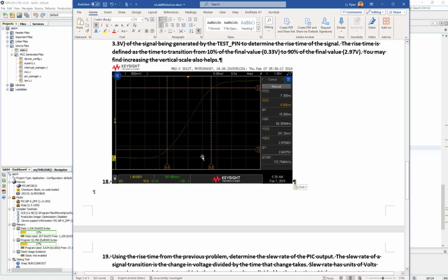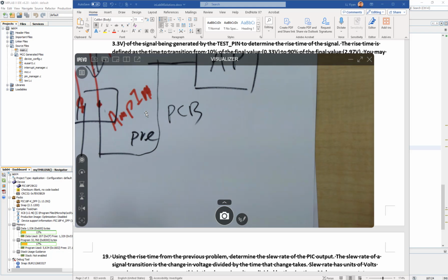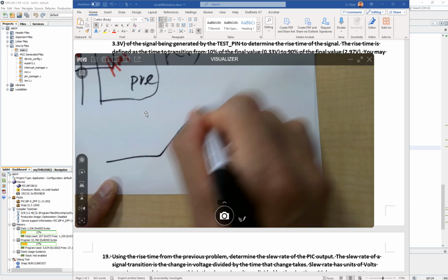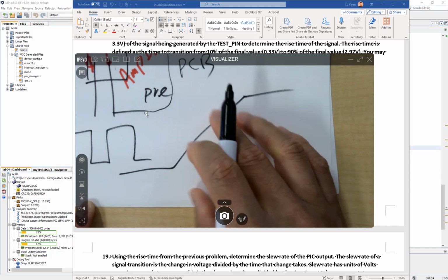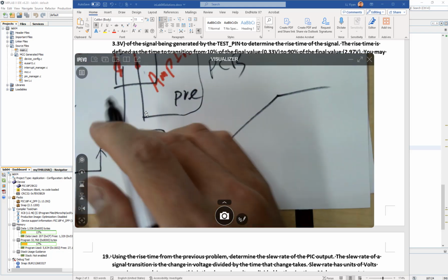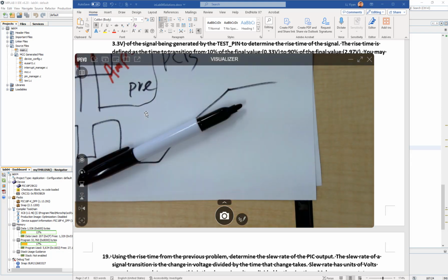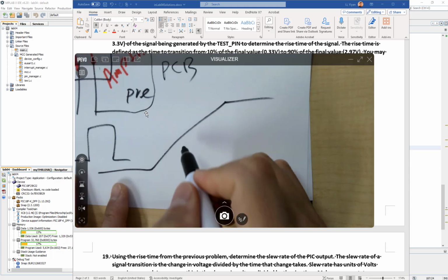And there's another thing, it's called slew rate. Have you learned slew rate somewhere else? No? Let me draw it on the paper. So many things to learn. All the pulses, if you zoom out, look like very sharp pulses, like infinite. However, they're not. If you zoom in, how do you zoom in? There's a time scale knob on the oscilloscope. Turn clockwise to zoom in. See this, it's a ramp.